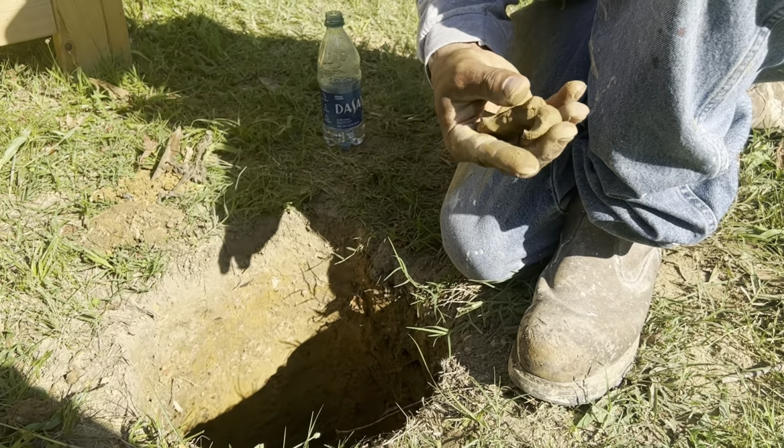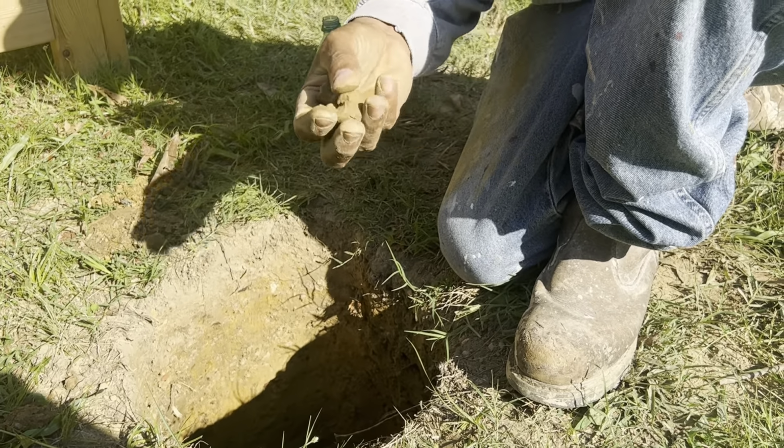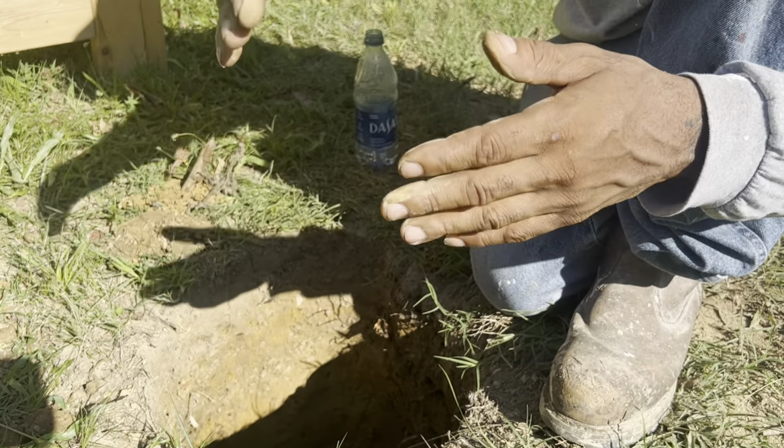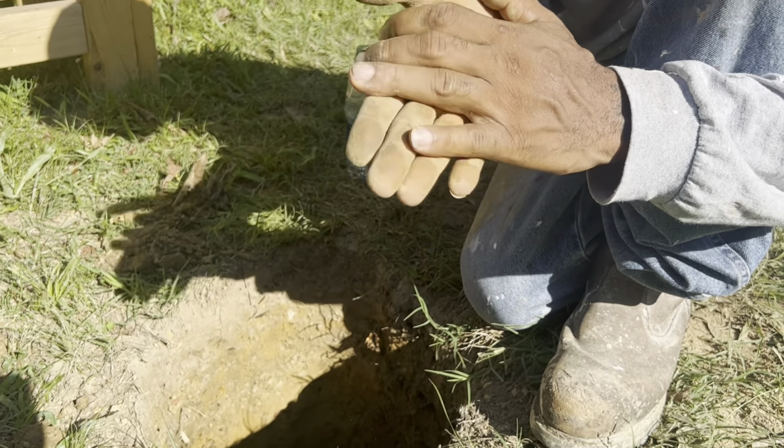Another little test you can do with the soil would be getting a masonry jar, okay? Get samples all around your building site, about four locations. Put that dirt in your masonry jar, okay? Put a little dish detergent in there. That's going to help the particles slip and then find their position, okay? And the sand will settle first, then the silt will settle, and then the clay will settle next, okay? Give it about a day or two to all settle, and you can use a marker to mark off that masonry jar to find your layers and get a percentage of how much of each soil you have around your location. That's just a simple way of finding out soil content.